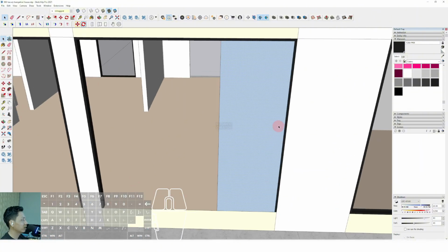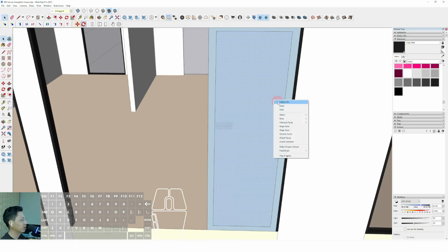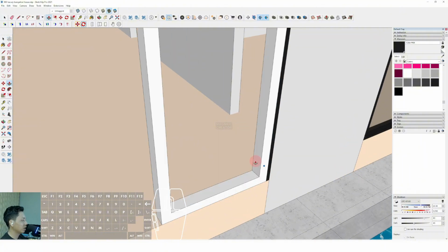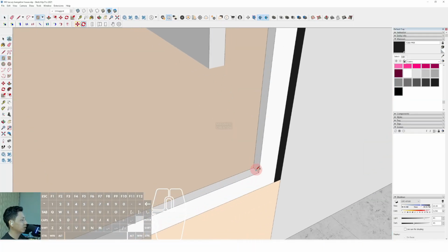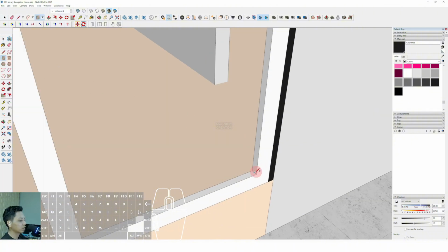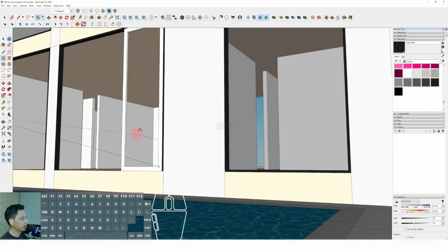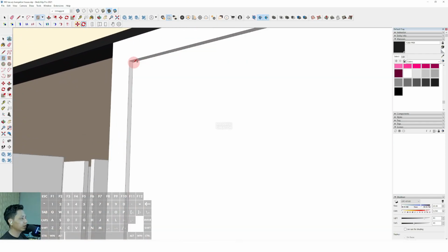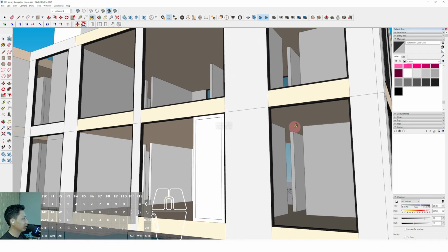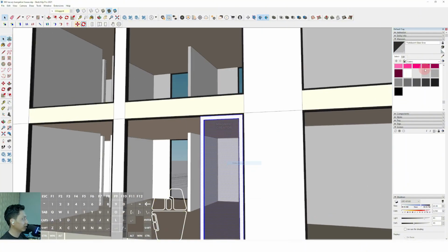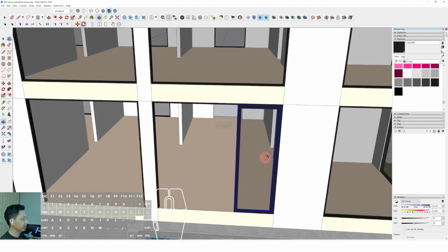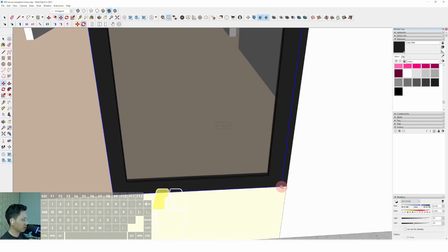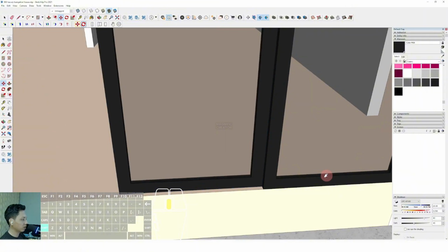Erase, then we can click the surface and offset it inside around 100 millimeter. Enter, click, right click and erase, and we can push it to behind around 50 millimeter. Sorry, we can push it until 40 millimeter and select the rectangle and click from this midpoint until the another midpoint of the top left corner. Then we can click assign materials and triple click, right click and make group and assign the frame in here. We can select move, tap control, place this position and place this position.